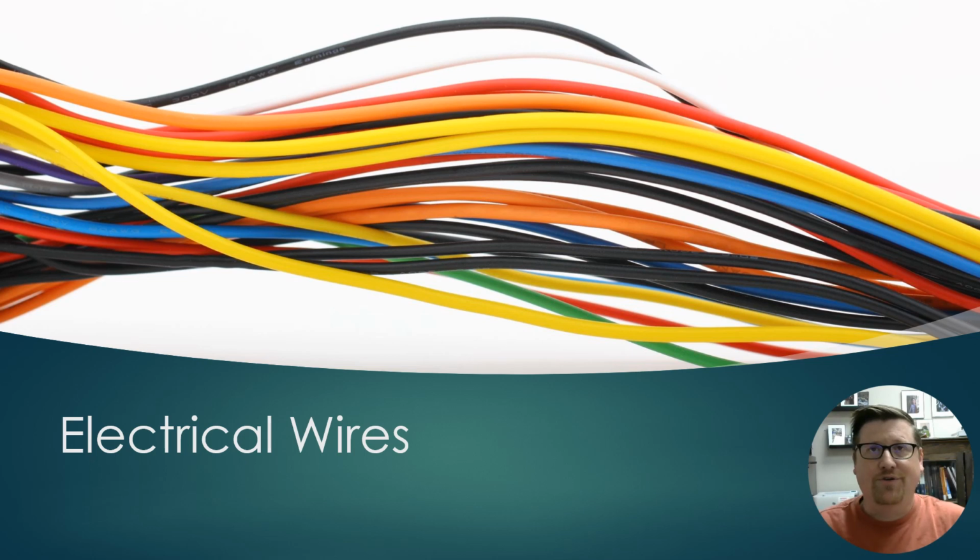We're going to have to consider the terminations, right, where that wire hooks up into a device. Is that device rated for a certain temperature? And so if it's not rated for a certain temperature, then we may have to derate that wire. We may have to use a larger wire or a different size wire based on the termination where it's going to be hooked up.